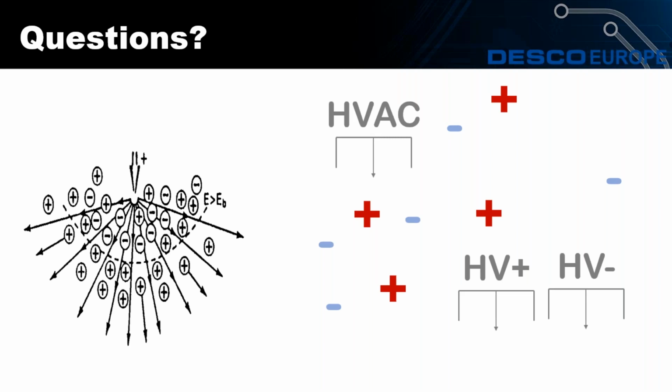So there's a question here about whether ionization can be used instead of grounding the work surface and the operator, and we need to say no to that. It's not possible to bypass normal personnel grounding and work surface grounding by using ionisers to neutralize the workbench and the operator. And the reason for that is it's simply too slow. So as Vaughan said earlier, charges that build up on a surface or an object will dissipate naturally over time. That's too slow for ESD control, so we use ionisers to do that.